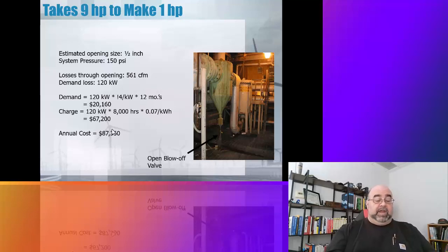Okay, and through a basic walkthrough of the compressed air system, several areas were identified. A complete understanding of the demand side of the compressed air system was not identifiable, meaning there were no plans, no drawings left, things like that. Baghouse airlines were not found and traced for air leaks. There was a significant pressure drop.